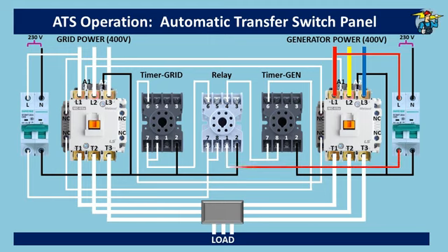Then, the control circuit breaker on the generator side allows power to the number 1 common port on the relay. You will see the lines to port 7 are still white, and the relay is not powered yet, but relay output number 4 is at normally closed position, and allows power at number 1 of the relay to flow to number 7 and 8 of the generator timer.